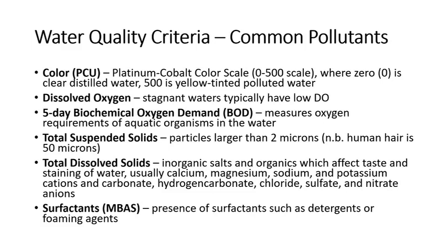This measures the oxygen requirements of your aquatic organisms in the water. So more or less, the DO should not be too small relative to your BOD. Otherwise, you will have your organisms dying in the water due to the lack of oxygen. The next is the total suspended solids. These are particles that are larger than 2 microns. So note that human hair is 50 microns in diameter.